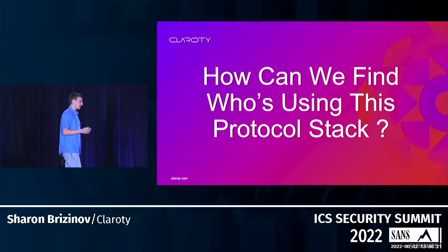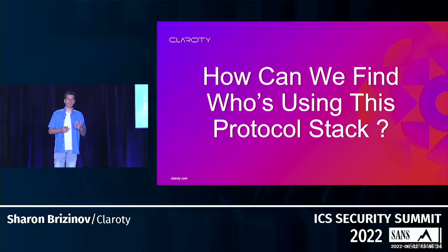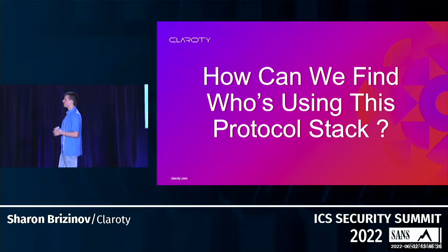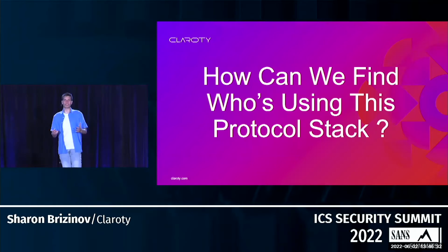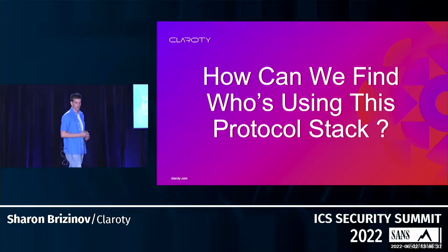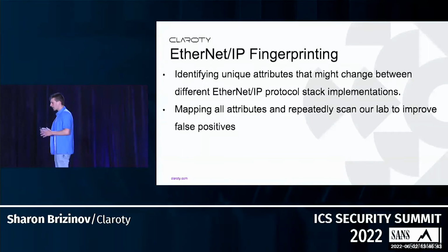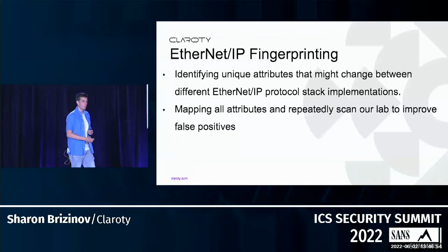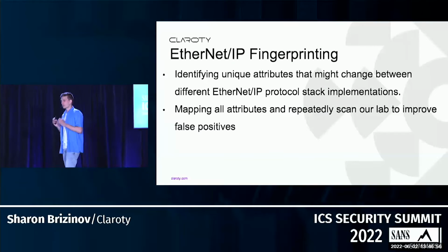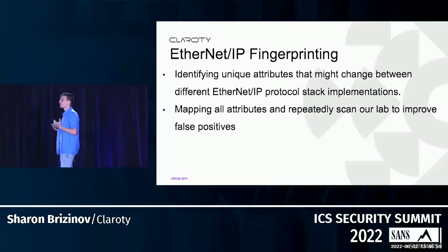Now, obviously, you should think about stuff like SBOM, software bill of materials. But as you might be aware, it's not easy to get the list of third-party protocol stacks in firmwares, especially in SCADA domain. So what we did, we came up with a pretty clever solution. We came up with a fingerprinter, a stack detector that was able to query remote devices and look at specific attributes of the Ethernet IP protocol to determine what kind of protocol stack is being used. So what kind of specific implementation is being used?